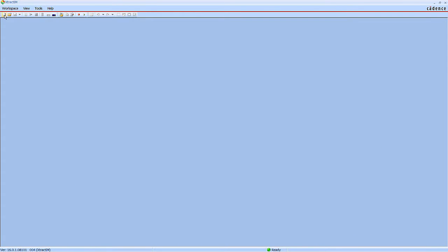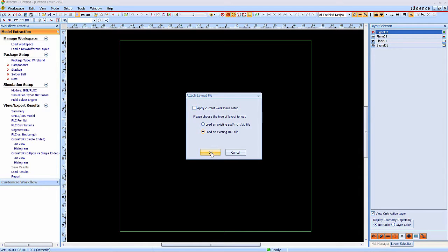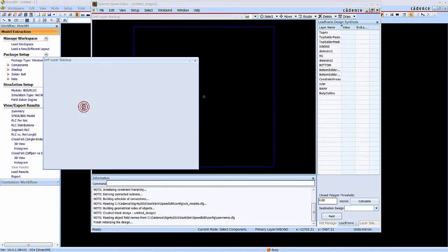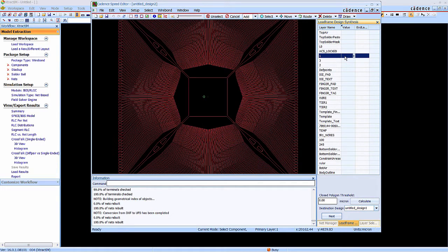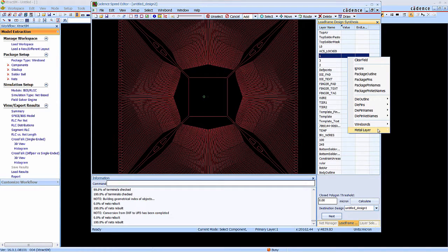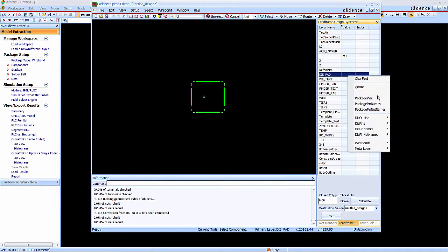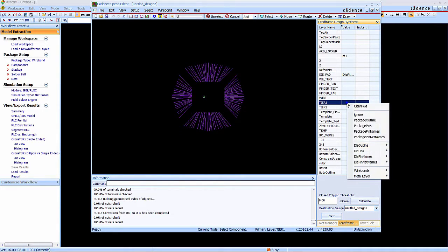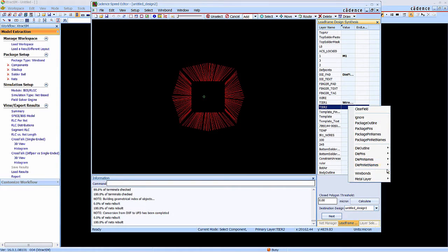Now we are in XtractRM environment. In the workflow, we are going to import the DXF file for the lead frame package. Cadence SPEED will be automatically opened up to handle the DXF to SPD synthesis. In this step, we are going to map the DXF layers to SPD layers, including inner lead, die, pad, and bonding wires.